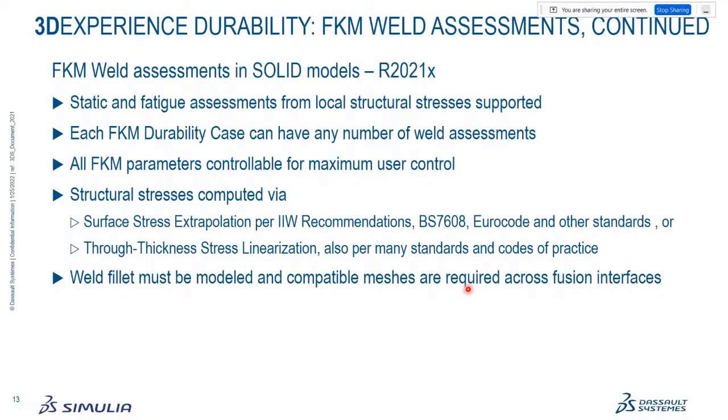You can have any number of weld assessments. If you have different kinds of welds, within each fatigue weld assessment, for example, you can define your fatigue loading specific to that assessment. And that, of course, can have multiple events inside that fatigue loading. But you can have a whole different definition of fatigue loading in a different specification of a fatigue assessment. Same thing for static assessments, right? So you can effectively do a whole lot of different assessments all in one shot if you just set it up all together.